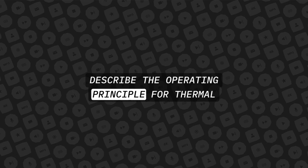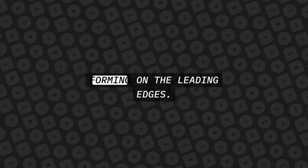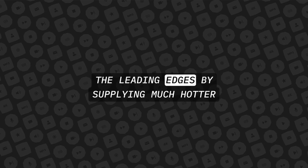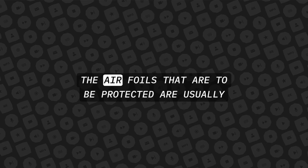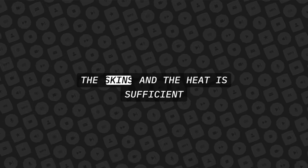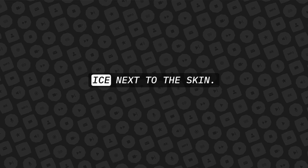Describe the operating principle for thermal anti-icing systems. Thermal anti-icing systems are used primarily for the purpose of preventing ice from forming on the leading edges. However, they are designed to also de-ice the leading edges by supplying much hotter than normal air for shorter periods on a cyclic system. The airfoils that are to be protected are usually provided with closely spaced double skin. The hot air is passed through the space between the skins, and the heat is sufficient to prevent formation of ice or to melt away any ice next to the skin.